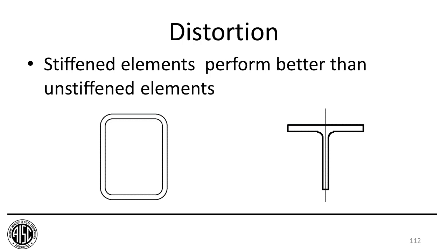I don't think there's a radius in there, but I think if you're putting camber to offset the gravity load in a beam, most fabricators are going to have the equipment to do that for normal size beams, say up to, I don't know, I'll just throw out a number. It's going to be different for every fabricator, but something like maybe a W24 or W27 they could probably handle, some of the bigger fabricators. If you get bigger than that, or if you have a really tight radius, you're going to have to go to a bender roller. And I really don't have a specific cutoff for you, but the fabricator and your bender roller can tell you more about that.